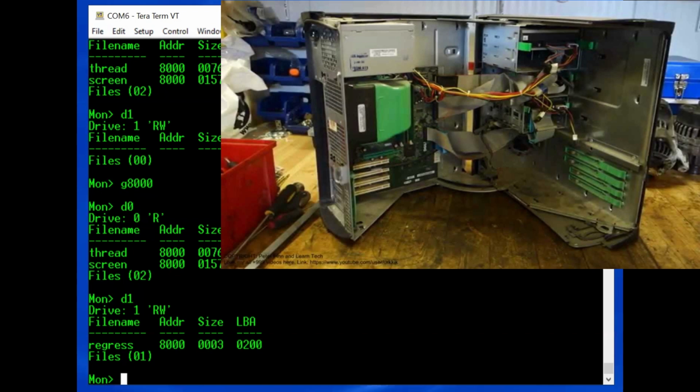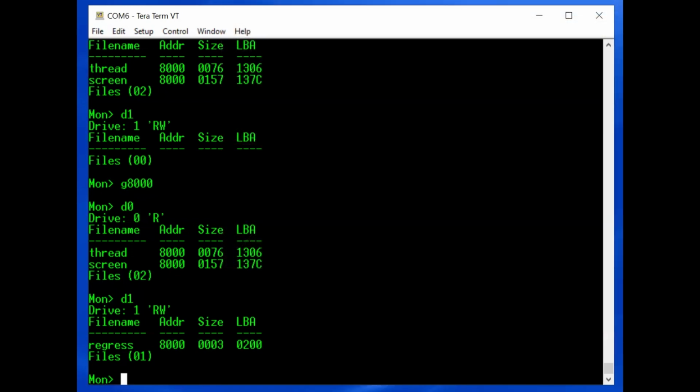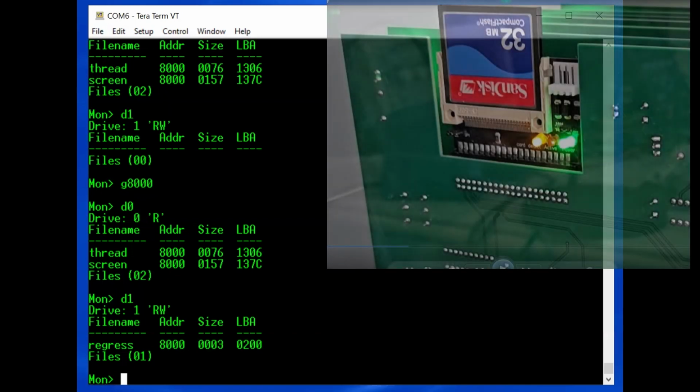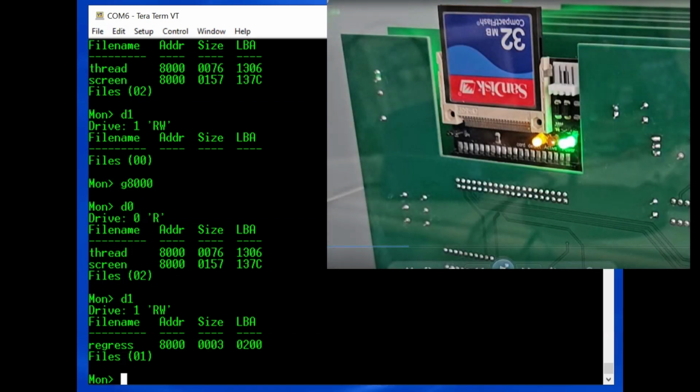So I picked the next best looking card out of the three that I had. And I wasn't going to do anything with the LEDs. The LEDs were also installed backwards on the other card, but I installed that into my Windows 98 machine and attempted to get that going. And lo and behold, I was able to get that card all working in my Windows 98 computer, albeit without the LEDs. So after proving that it was working there, I desoldered and soldered in three new LEDs the correct way. So hopefully the card was good.